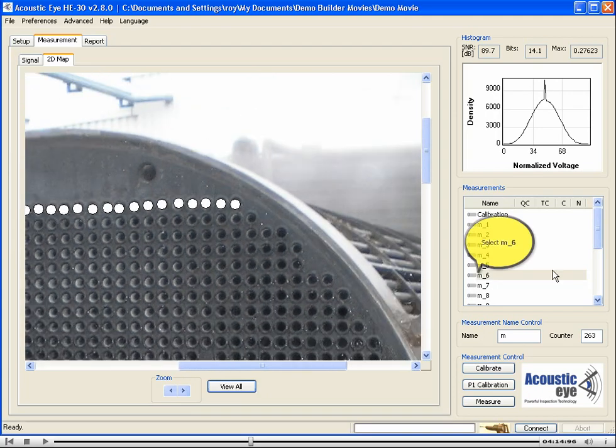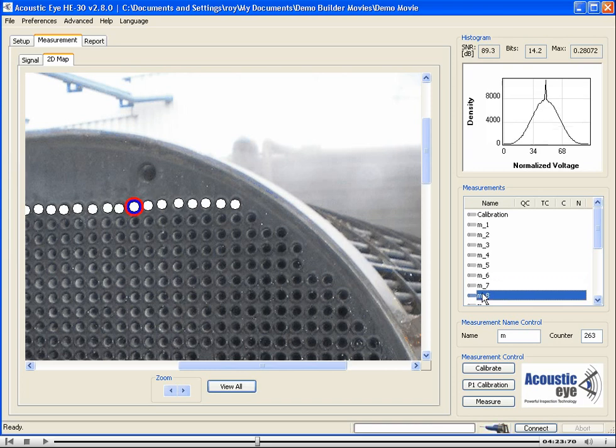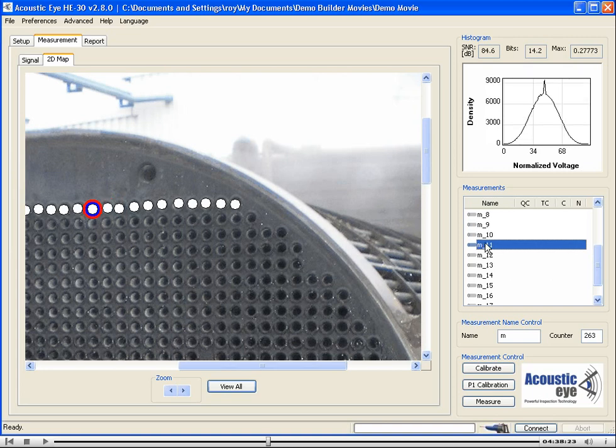The main advantages of the APR system is first its speed. It takes less than 10 seconds to measure a tube, and also, by using the fact that the sound wave that we are generating is traveling in the air inside the tube and not on the tube material, it means that we are not dependent on the tube configuration and conformation, meaning that any tube shape, U-tube, fin-fan, spiral, S-shape, and any tube material, stainless steel, copper, brass, PVC, rubber, you name it, can be inspected.